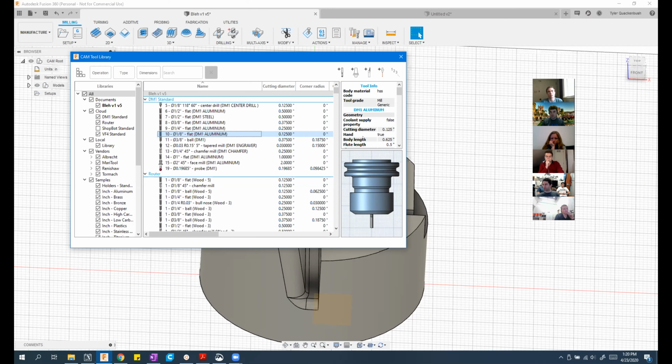There are still some parts that are out of date, but all the tools are correct. Cool. Never trust stickouts. I second what Tyler says. They change job to job. Mastercam actually does it interestingly. The stickout is determined by your operation. It's not inherent in the tool library, so they assume that it's going to be operation specific. So you can put that in your operation. Cool. But yeah, don't trust stickouts.